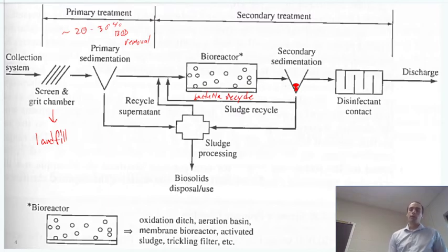And so when we apply them to land, we have a whole system to say, okay, you can't apply more than X mass of biosolids ever in a lifetime for this plot of land. And so we have some system where we can use them for a time, but we have checks and calibrations to make sure that we don't ever get to a point where we are contaminating beyond a reasonable amount. So it's a kind of nutrient recycle, which is great, but a trade-off there, we have to be careful with accumulating contaminants.